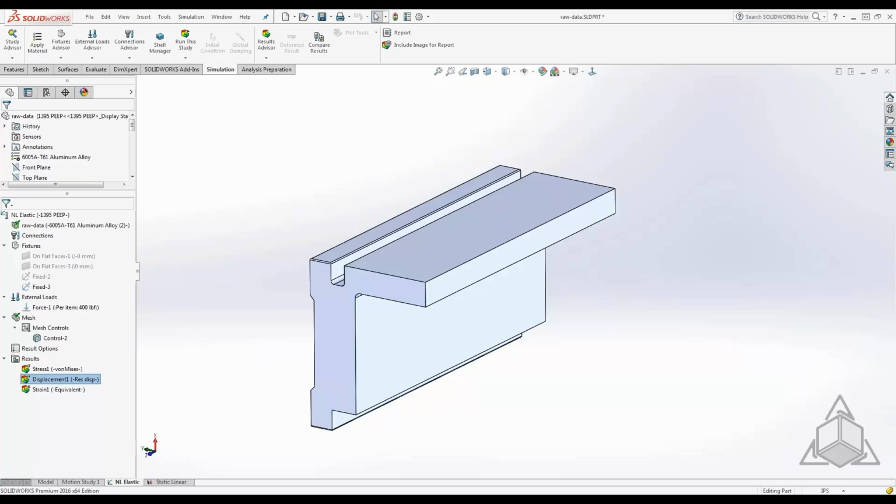So yes, it would make sense maybe for you to machine it down to its minimum thickness, and then put it on your tensile stress machine, gather those results, and put them in SolidWorks Simulation. That allows you to make appropriate changes, or even test the different boundary conditions required for the part, try to figure out the right factor of safety for the part, and run fatigue analysis on the part as well.